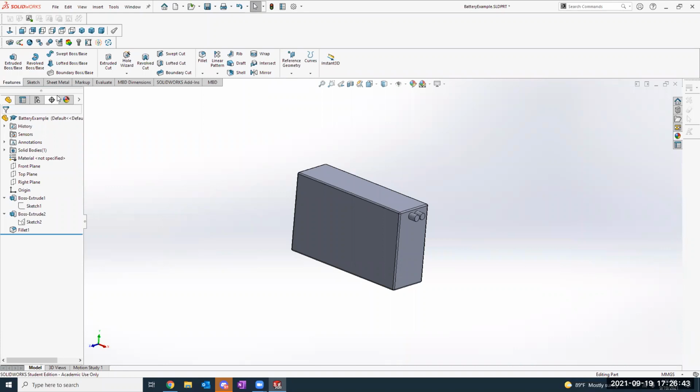Right. Well, if you're designing a waterfall, then you can show it out from the very top because the top has no finish. Yeah, I'm not sure about a completely enclosed one. The way to do that might just be to show it and then put that face back in afterwards from the sketch. Or you could also start with a plane. You might create a plane with a part of the end, and you might sketch inside of that plane. Oh, like offset the plane, right? Yeah, you offset the plane a little bit inside the part and then sketch it there. And then cut away.